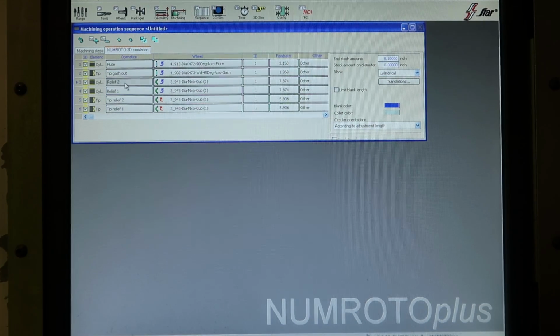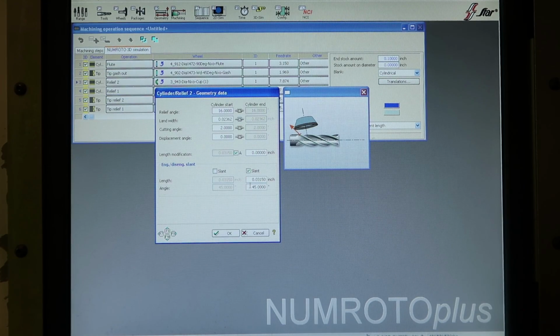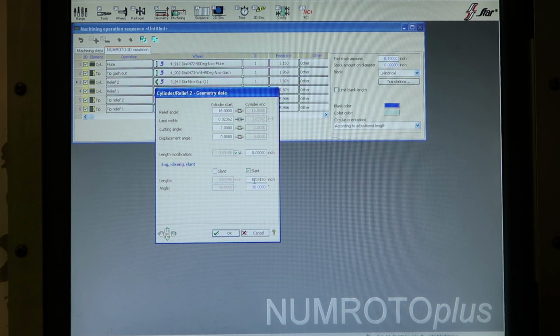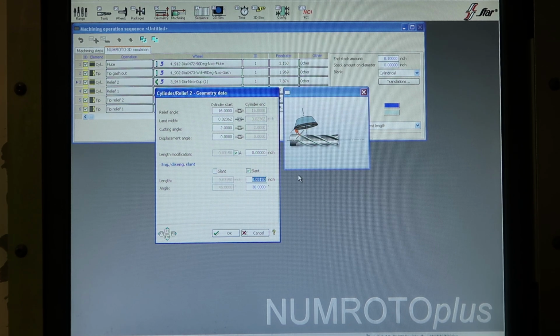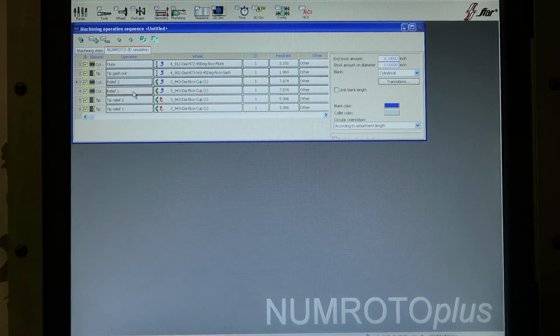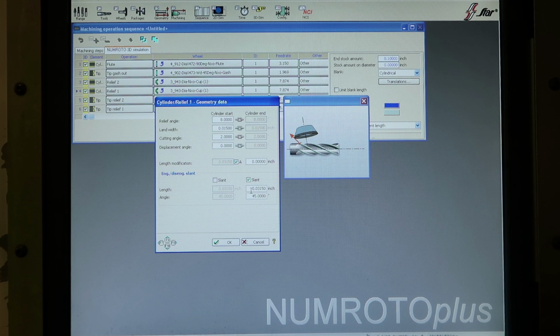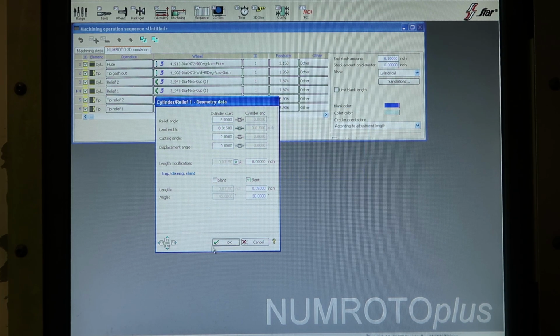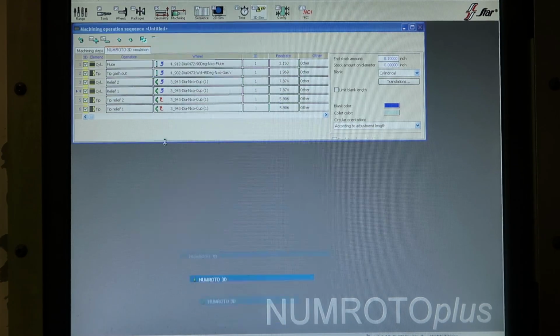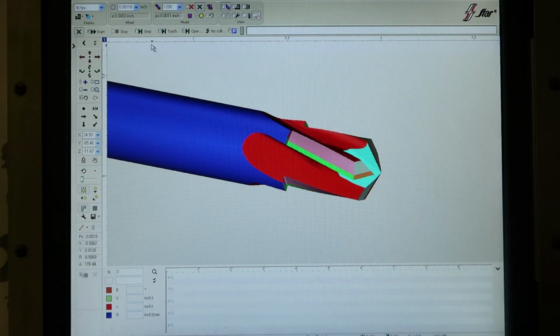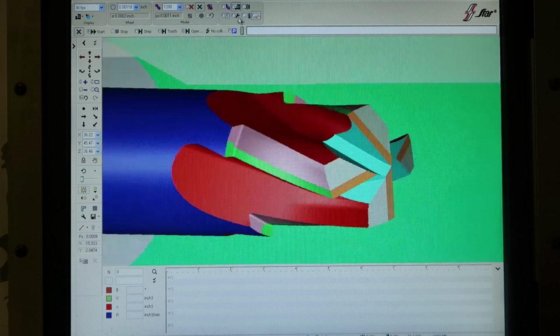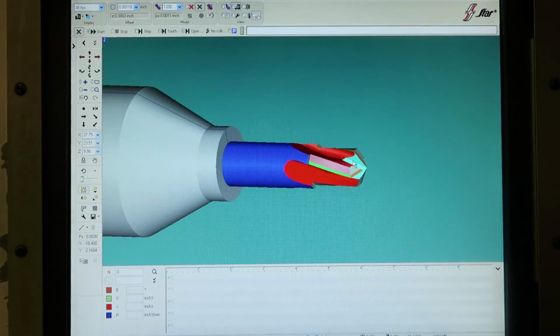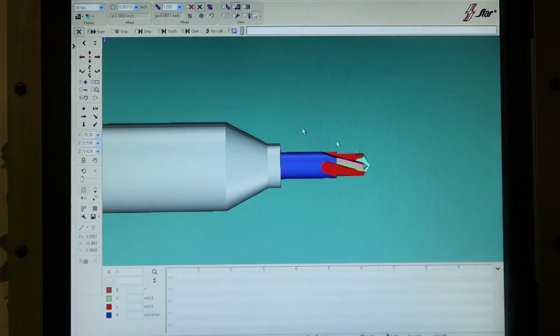So we're going to also lead off of these at the 30-degree angle to make our 60-degree chamfer. I'm going to make that about 80 thousandths long because it'll need to be longer because of the angle. And this is about 50 thousandths long at 30. So that might be enough to do this. Let's just see. Let's go back to this so we can see the grinding wheels and everything, the simulation.